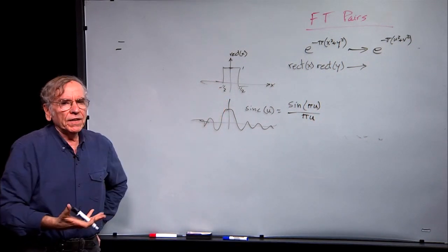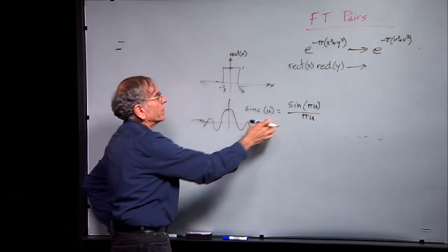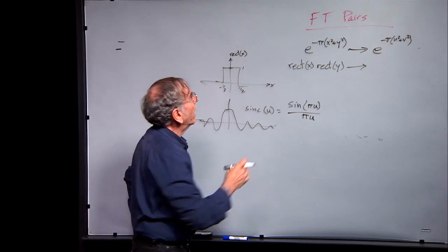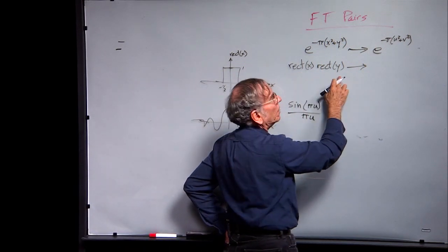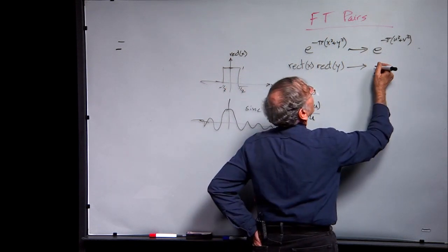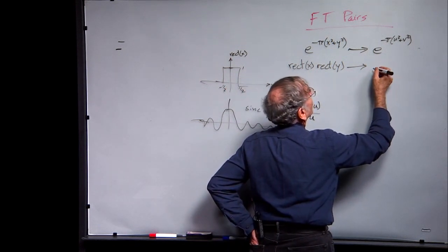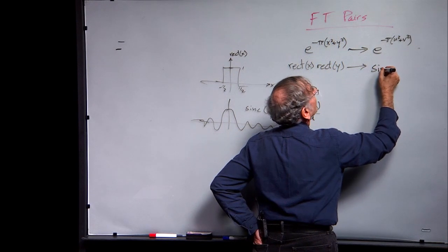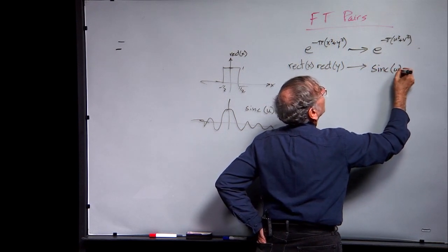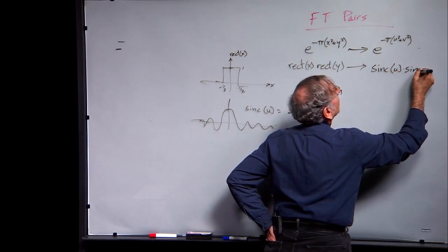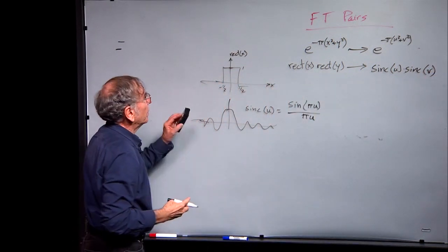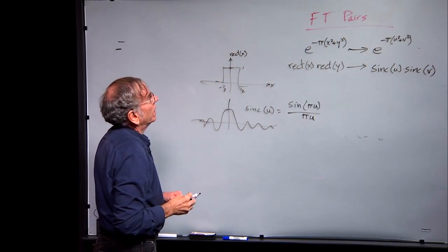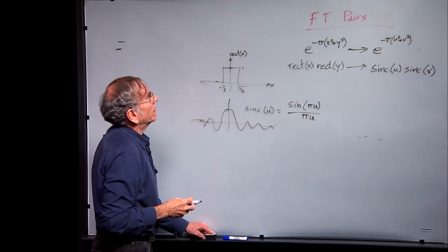There are two definitions of the sinc function in the literature, and this is the one I'm using here. And so it turns out that the Fourier transform of the square rect is a square sinc function. That is, it's going to be sinc of u times sinc of v. So we don't have big surprises here yet.